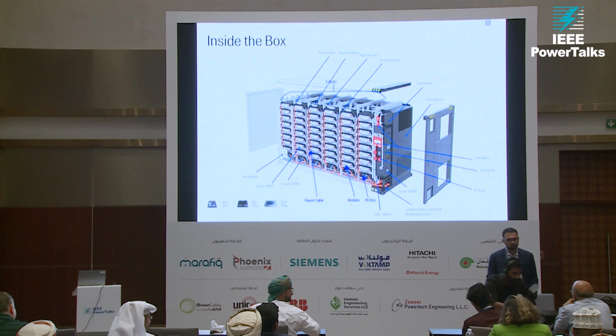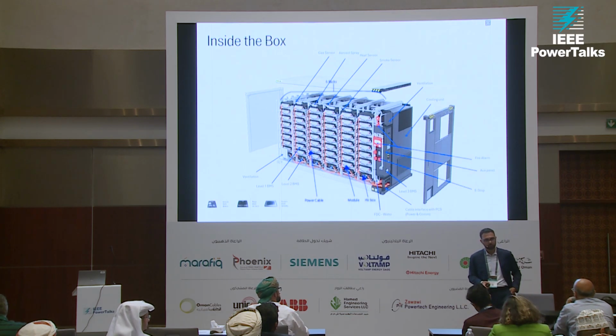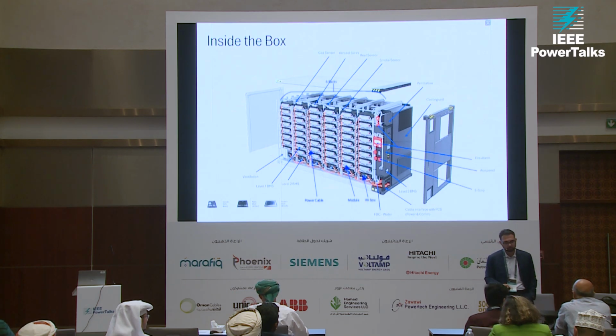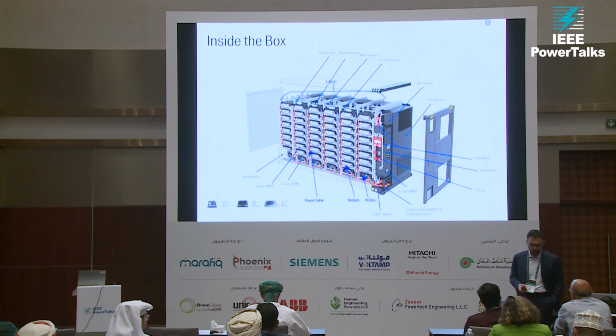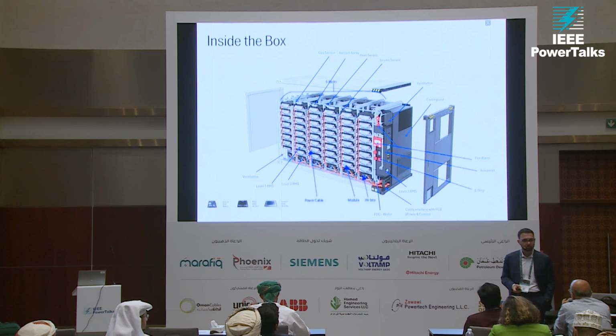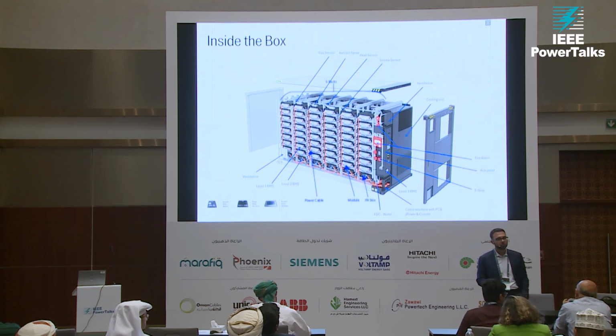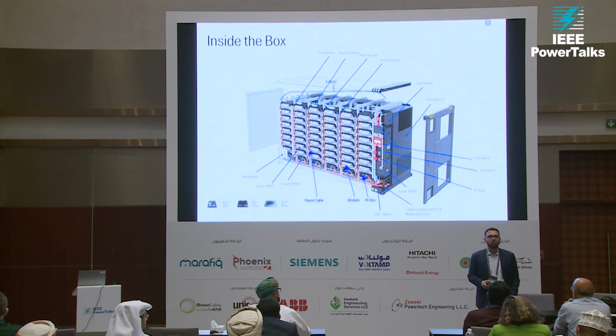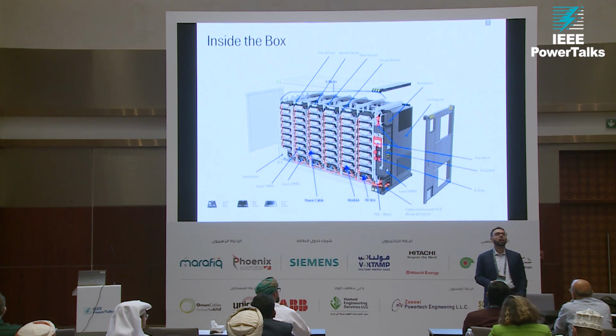Is there any need of any specific equipment, like what we call hazardous area equipment, like Zone 2 type? Normally in the oil sector, wherever we are having hydrogen gases, we use specific equipment which is suitable for Zone 2, meaning area classification, right? Meaning flame-proof equipment or increased safety. So is there any need of using any such equipment near these installations? Are we following any hazardous area classification?